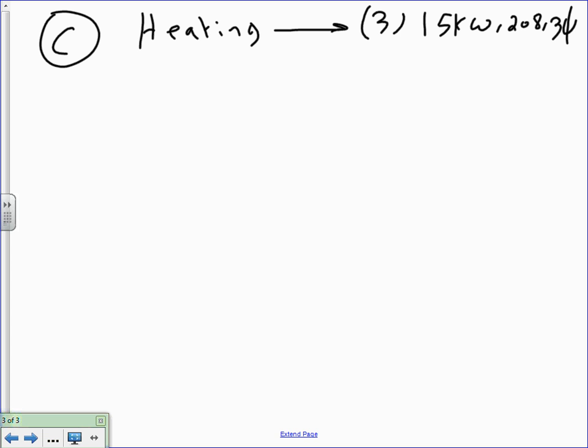By the way, unless I tell you it's 3-phase, the loads are single phase, right? So it's very important for calculating the neutral later on to know is it single phase or 3-phase. That's why I put the voltage next to them, because you don't know. Are they doing 15 or 115? 15 kW. Oh, I'm sorry, 15 kW.